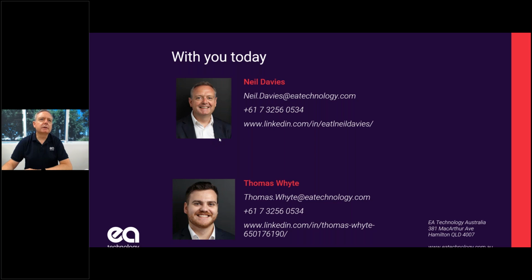Okay, where does the majority of cost to customers come from? Online PD equipment or data analysis and expertise? That's an interesting one. Thank you, Kyle. It's quite a simple technique to deploy. So with online PD equipment, actually taking the measurements is relatively straightforward, using the capacitive probe, using the ultrasonic sensors and things like that. What really needs to be done to get the best value is to do that in a very good logical manner. And the value is probably coming from the data analysis and the expertise.